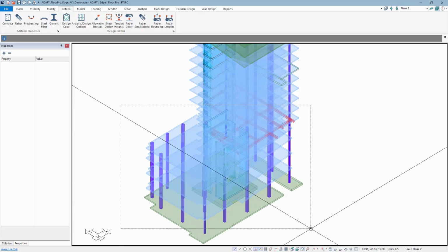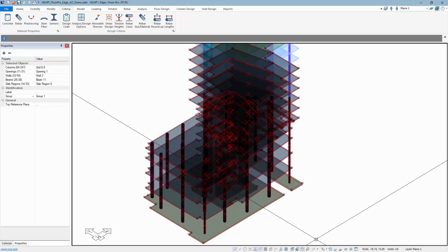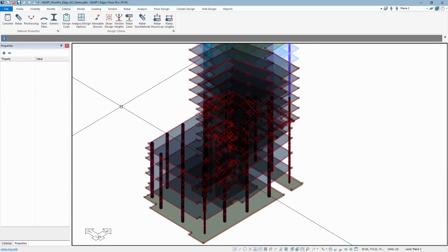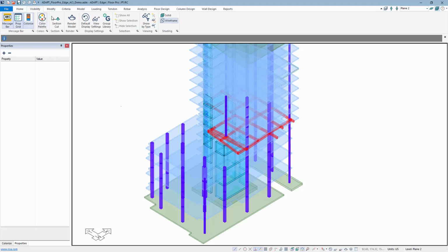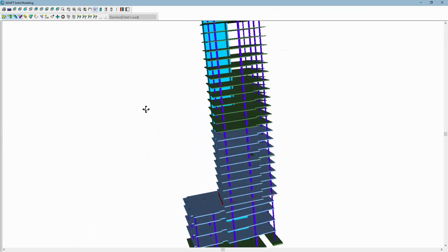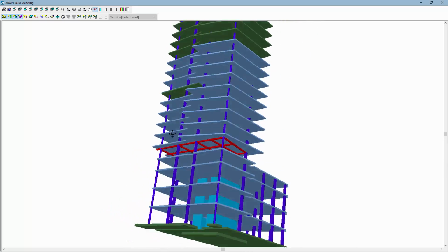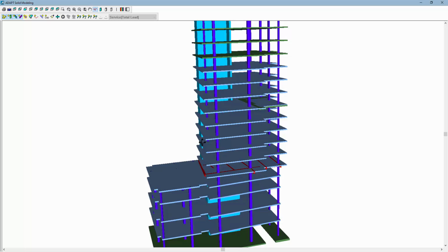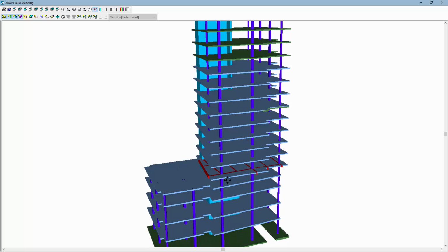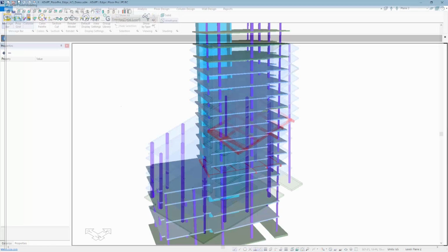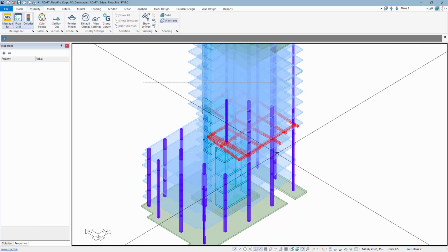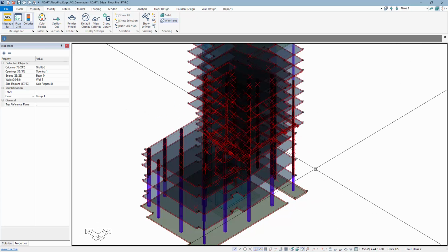If I select through all of this, let's say I wanted to change some of these beams at level 6. We're going to go back and just look at that level. We have a series of beams there at this level. Those beams are colored in red. And so I want to modify those beams to a specific size, for example. If I just window through this, it's hard to select those beams unless I switch to single level mode and select by type beam. And that's still an option. We could still do that.